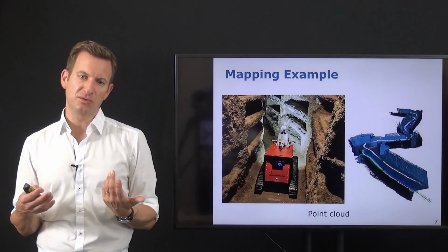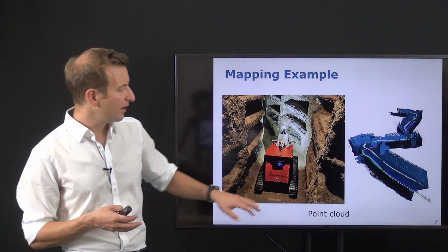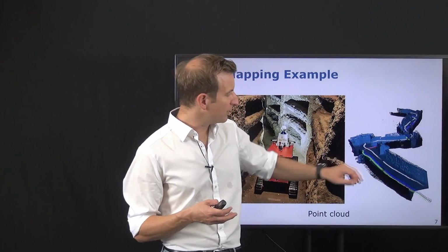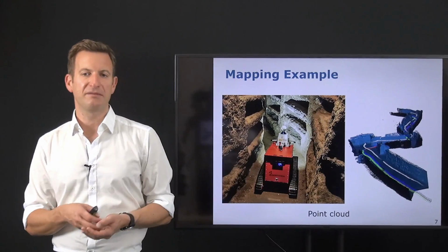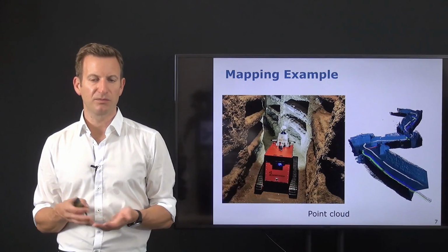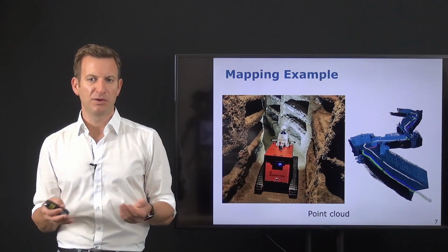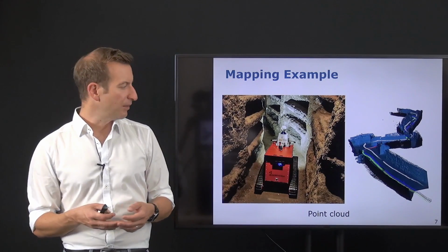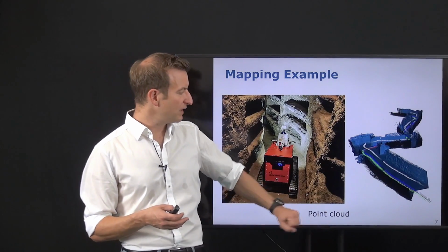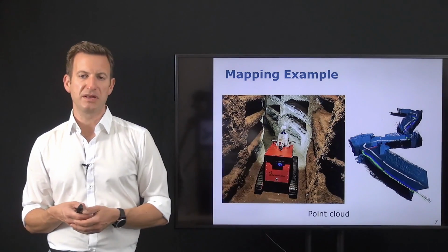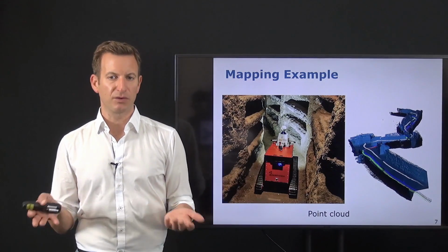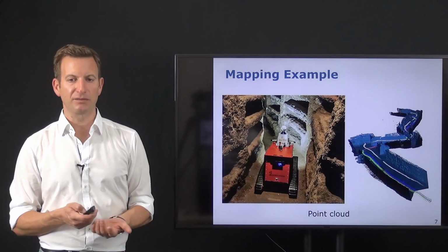For that, you need to build a 3D model of the environment. You can see here a part of the point cloud that the system was generating while navigating through these tunnel-like environments. This is also a map of the environment, a volumetric representation, although you may not call a point cloud really a 3D model, but we could use this 3D point cloud data to render, for example, a 3D occupancy grid map.